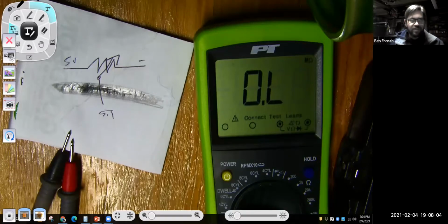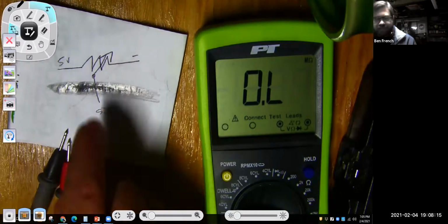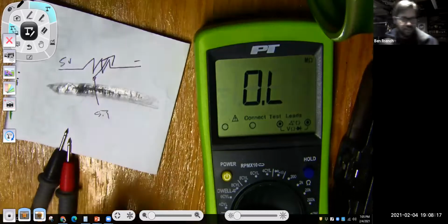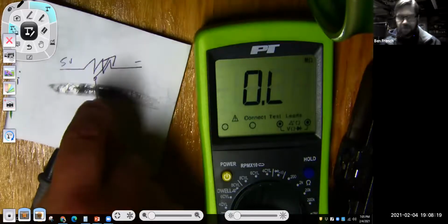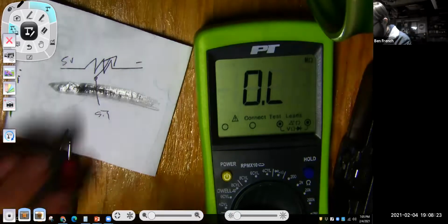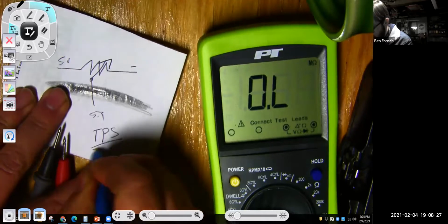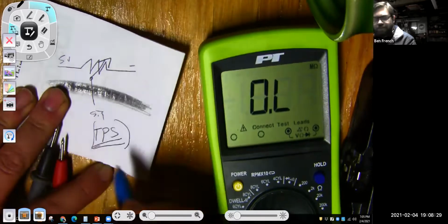Usually if it's a throttle position sensor, that's somewhere around a quarter throttle, third throttle. So if you had a car that was fuel injected and it had a throttle position sensor like this, and it has a hesitation on acceleration, I'm going after that TPS. Okay, so that's a good example of an old school non-Hall effect throttle position sensor, or TPS.